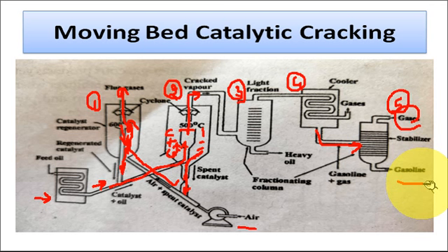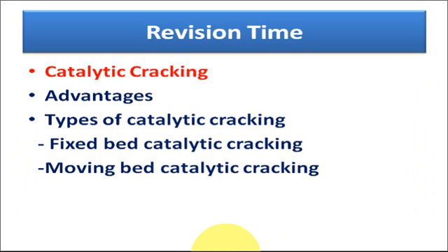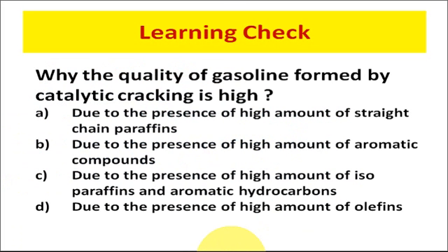I hope you will be able to understand both of these processes now. Now, what have we learned today? We have learned the advantages of catalytic cracking and the types of catalytic cracking, in which in detail we have discussed the fixed bed and the moving bed catalytic cracking.